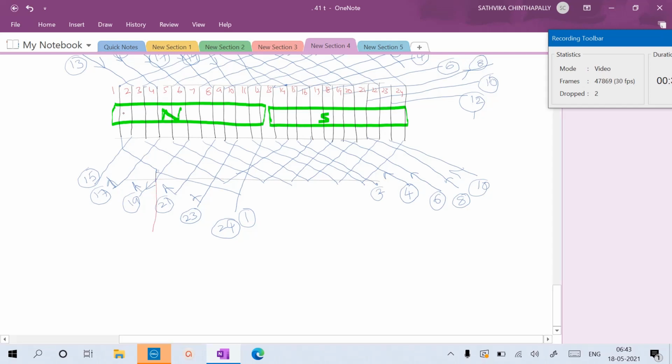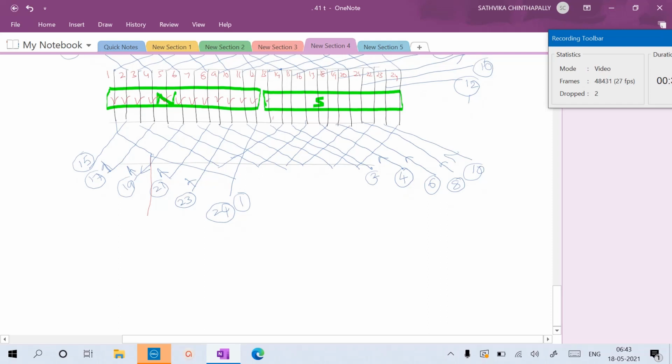So here it also indicates the current directions in the conductors. Let us assume that under the north pole all currents are coming downwards. Okay, so indicate here the current direction up to the 12th conductor. Okay, so this one, this one, this one, this one. Now it indicates the opposite direction, current upward.